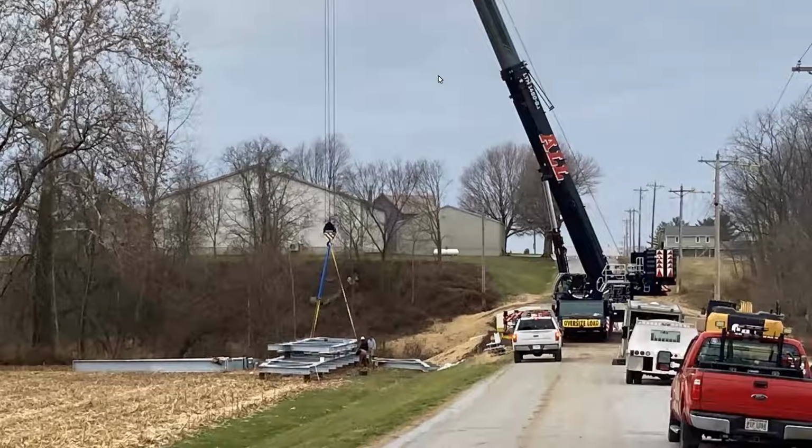And once those trusses are set, we set the first one, like I said, guy it off, stabilize it, bring in the second one. While we're holding on that, we may be able to put floor beams in, or we may guy it off too, and then use the same crane for erecting the floor beams.